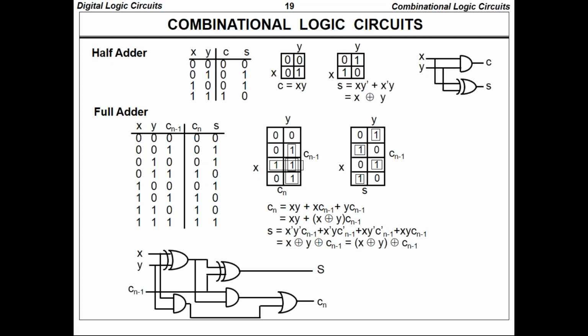They run on a clock. Actually, the main thing is that in a combinational circuit, the output depends on the present input alone. That means there is no feedback between your output and the input. A clock is a necessary thing in a sequential circuit. But generally, if the output depends on the present input, then it is a combinational circuit.